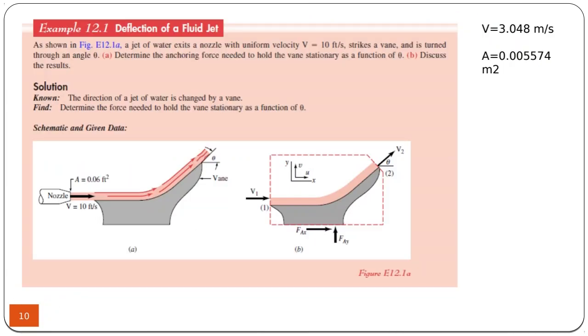As an example, water flows over this nozzle. It comes horizontally and it leaves at an angle. So it's asking, what is the reaction force to be applied to the nozzle to keep it in place? Otherwise, if there is no force here, it would move, right? Because of the momentum change.